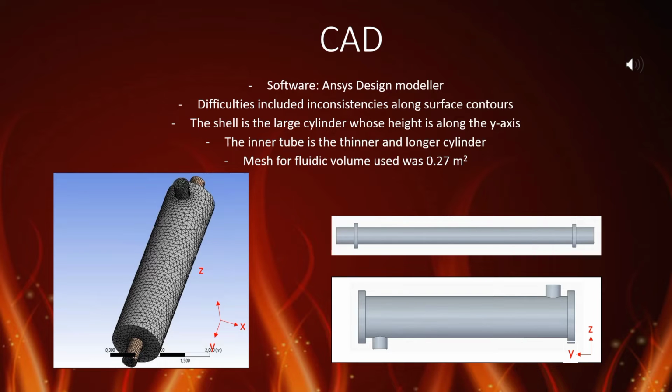A mesh of 0.27 square meters was used as this was sufficient for mesh-independent simulation runs. Numerous iterations were done due to the computer-aided drawing showing errors and inconsistencies upon simulation. After revising these results as a group, a consensus was reached that the results were erroneous. It was later found out that the model contained gaps that output somewhat strange results. Inspection of the model led to a smoother and more consistent model which simulated the scenario to an acceptable degree of accuracy.